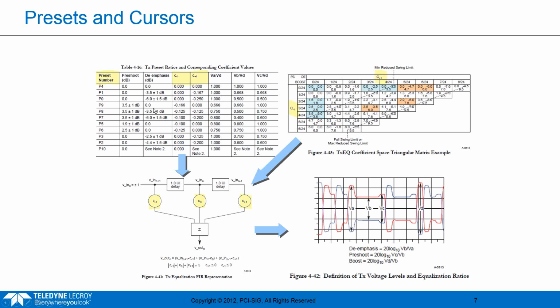And I see that in some cases that's done because the receiver equalizer for that device is really good. Maybe they have a 5-tap DFE or something that can really handle almost any signal it can get. In other cases, it's done just, I think, because it's cheaper or less effort. And in a lot of those cases, you see that it doesn't work out. They can't pass these tests by just hard coding the preset. So the minimum is 1. The maximum is every combination, so might be up to like 42.